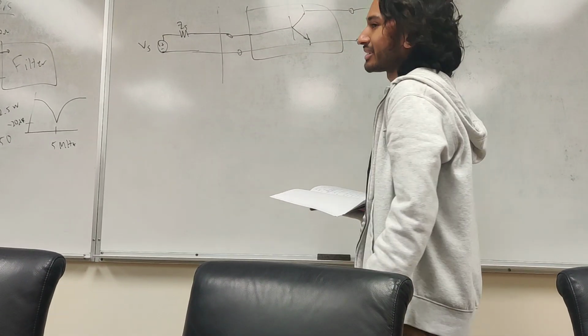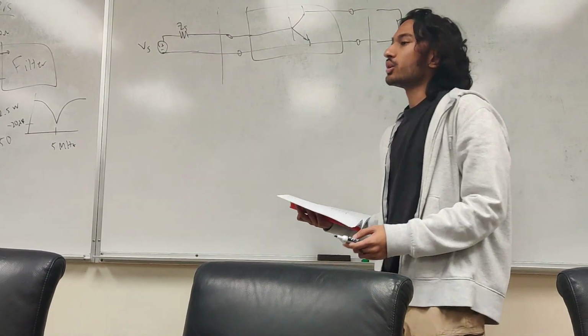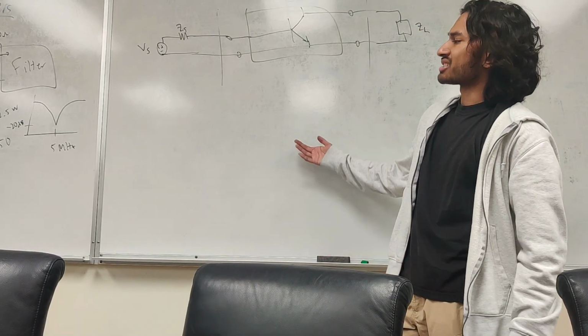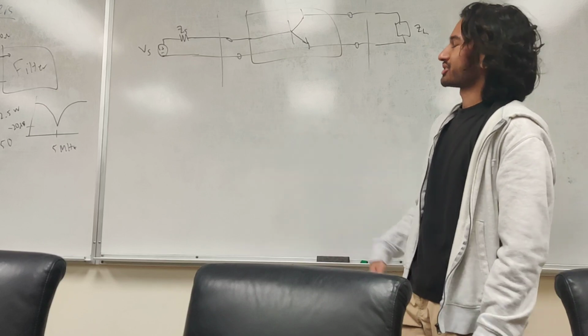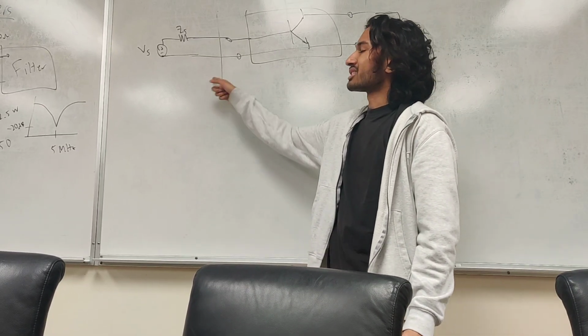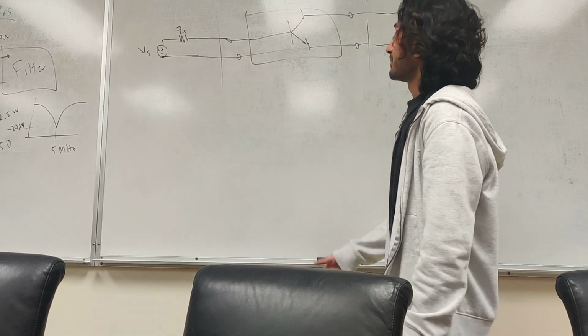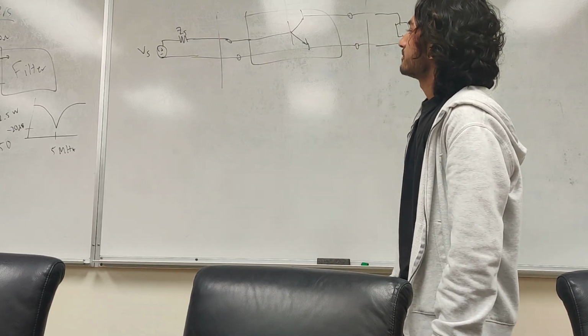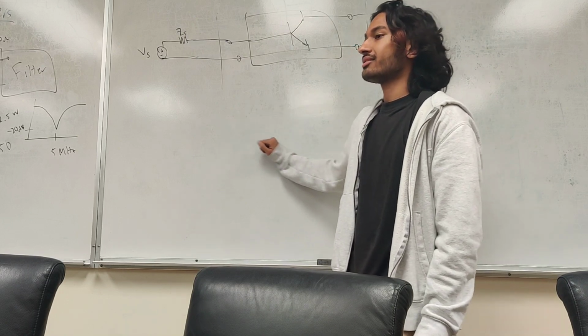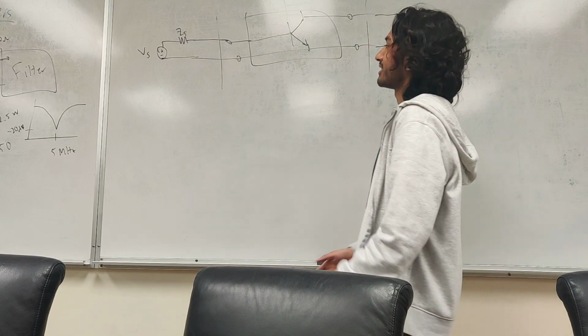And this is where it gets kind of complicated. Do you guys remember the reflection coefficient from 1.1a? It characterizes, it's kind of how S parameters are. There's a relationship between S parameters and reflection coefficient. We're going to write some reflection coefficients out because we're going to assume these are not matched, right? And that means signals can reflect. Okay. Again, are we talking about actual reflection here? Not yet. We will get to that.